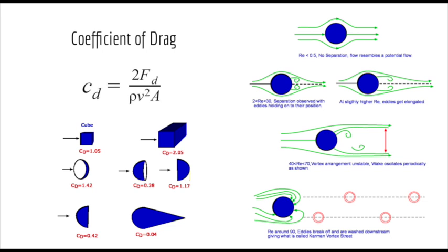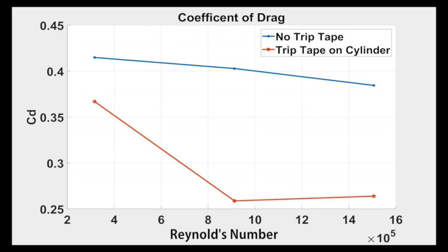And as for the Reynolds numbers for our tests, at 150 RPM, it's 3.165, at 400 RPM, 9.124, and at 650 RPM, 15.064. For this plot, we calculated the total drag force experienced by the cylinder by summing up all the individual pressure forces in the x direction read from 25 ports. We end up with 6 values for the coefficient of drag, which are in the accepted range, which is coefficient of drag is greater than -1 and less than 1.